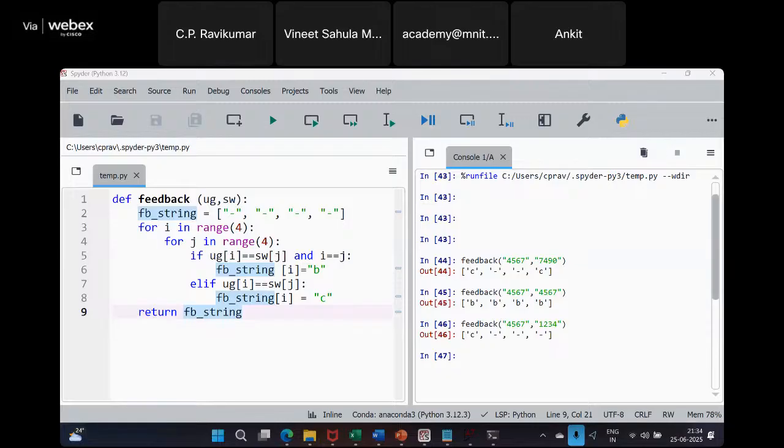Dave is asking, sir, is VLSI done in C? Hardware C used to be there, but I don't think it took off. Okay, hardware C is not, to my knowledge, used by anybody, right? Verilog is still very popular for design because you can take it to synthesis. You understand? If you are only interested in verifying, you can use things like hardware C, etc.